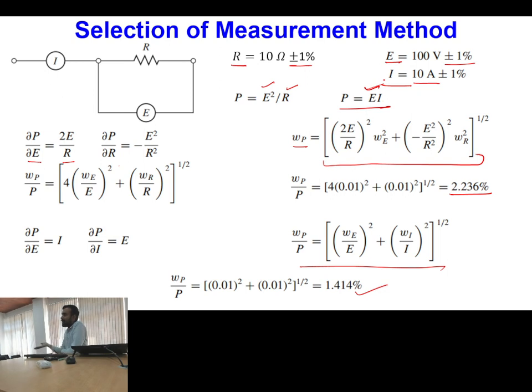You have to start from the very first thing. Whenever you are designing an experimental setup, first you have to identify what measurements you want to make, and in which range of measurement. Once you have decided the range, say you want to measure flow rate, and you have decided that in your experiment you will be controlling flow rate from 0 to 100 LPM, you will choose the flow meter as per that.